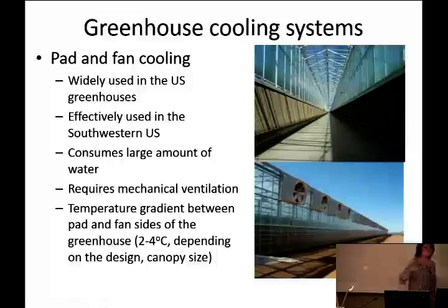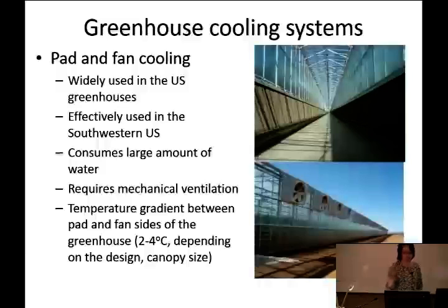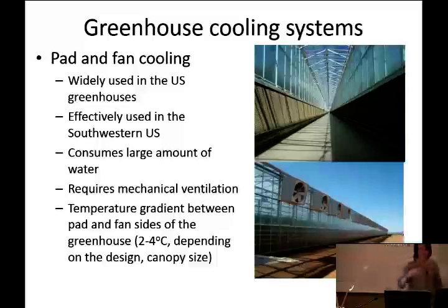I think the cooling capacity, how much delta T or temperature deficit you get through the evaporative cooling, is pretty much determined by the wet bulb temperature. So how much moisture the intake air is containing. Whether it is a little bit warmed up in this corridor or walkway doesn't really affect it, because it's the moisture content. If you have fogging in here, it would definitely affect the cooling efficiency. But as long as there's no moisture change through that process, the cooling efficiency is the same.